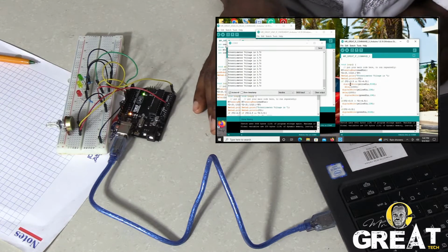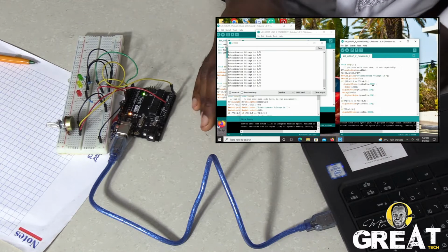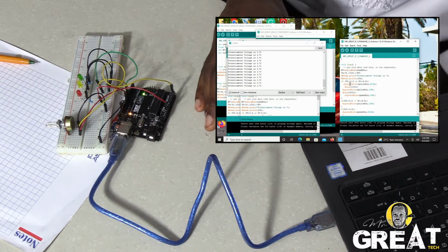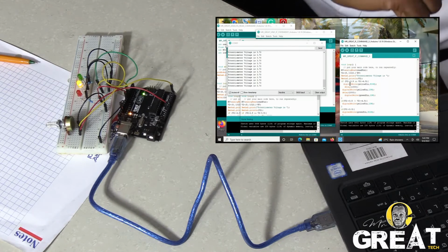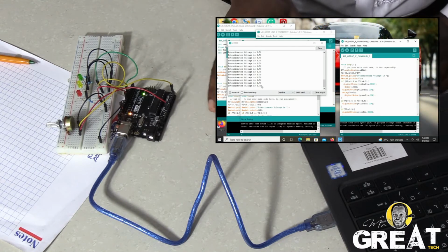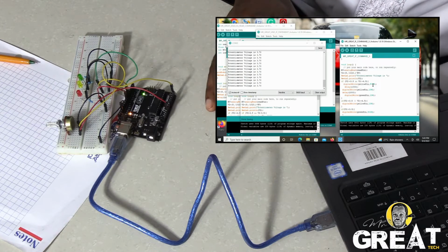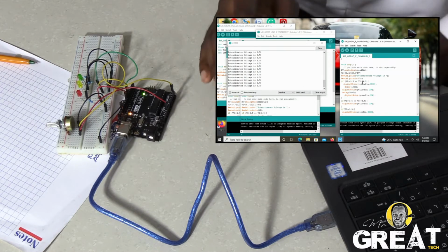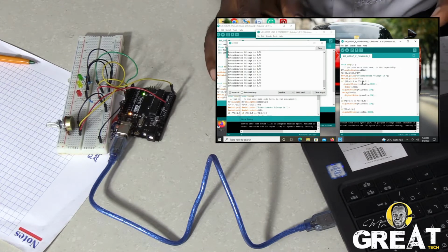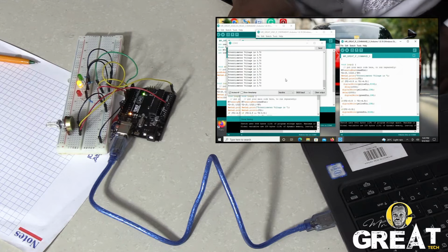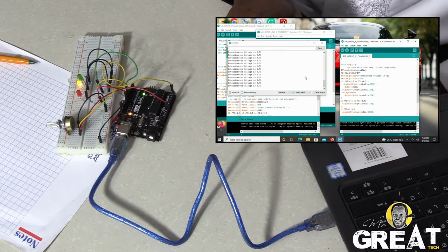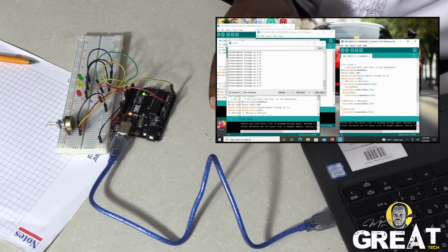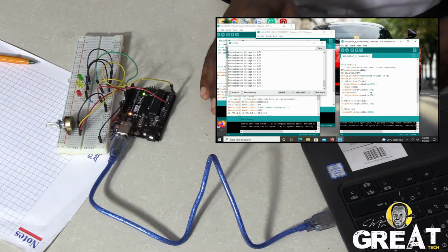Okay, so now let's see digital write yellow pin high when V2 is greater than 3.5. I have 3.7, that's why it's high. And also equal to 3.5. So it's more than 3.5, it should be high. And V2 less than or equal to 4.5. So it's less than 4.5, but it's not also equal to 4.5. It's still less than 4.5, so it will still turn it high. Okay, so let's move ahead.